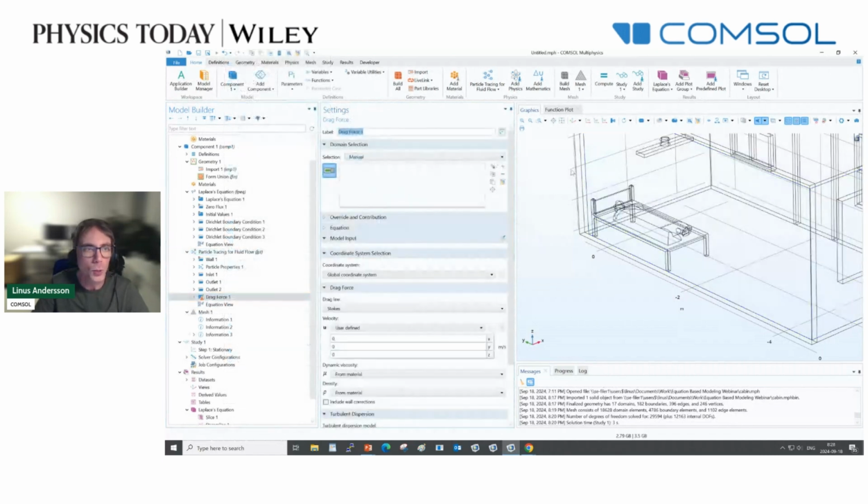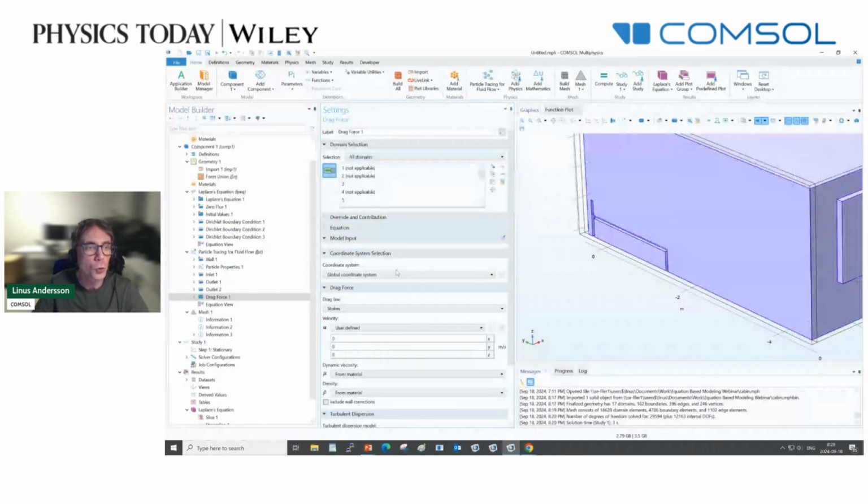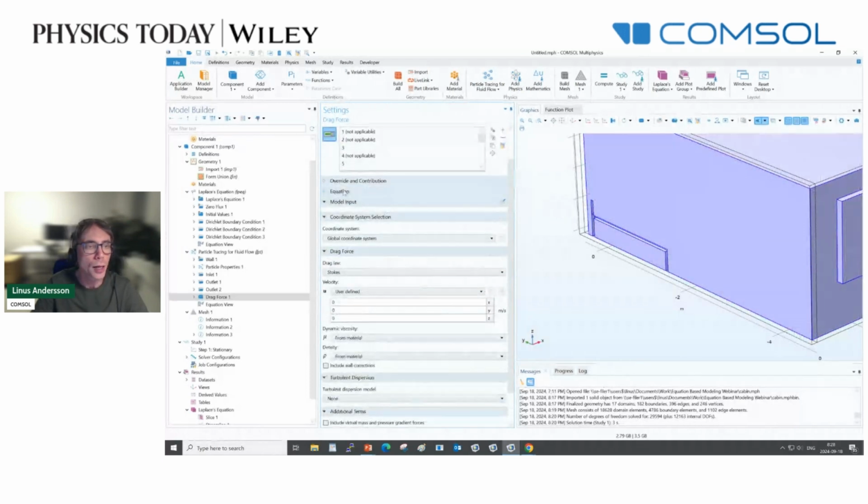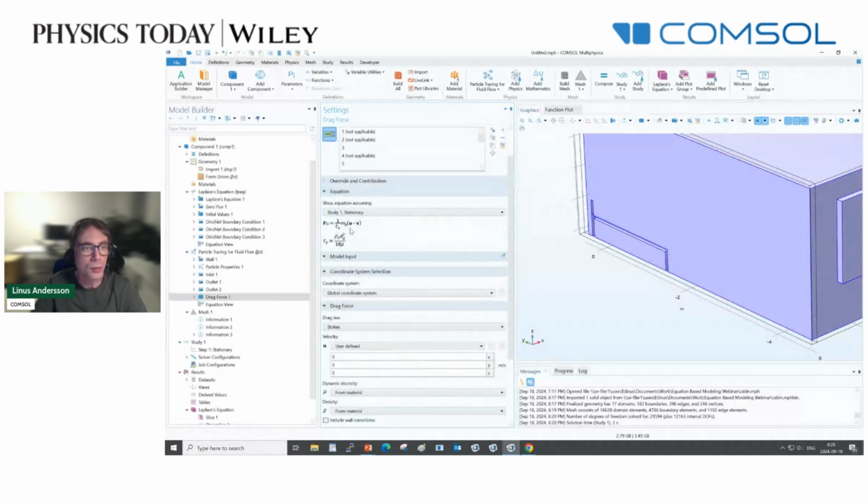In fluid mechanics, we use drag forces all the time for fluid particle tracing. And the equation, which you can see right here, looks like this. It features 2 different velocities. It's u for the fluid velocity and v for the particle velocity. And the force will act to try to make those the same. So the particles will propagate with a velocity that's similar to the fluid velocity. And once again, our fluid, so to speak, is this attractor gradient. This is what gives us the advective component. So I'll just fill that in again. Vx, Vy, Vz, like that.